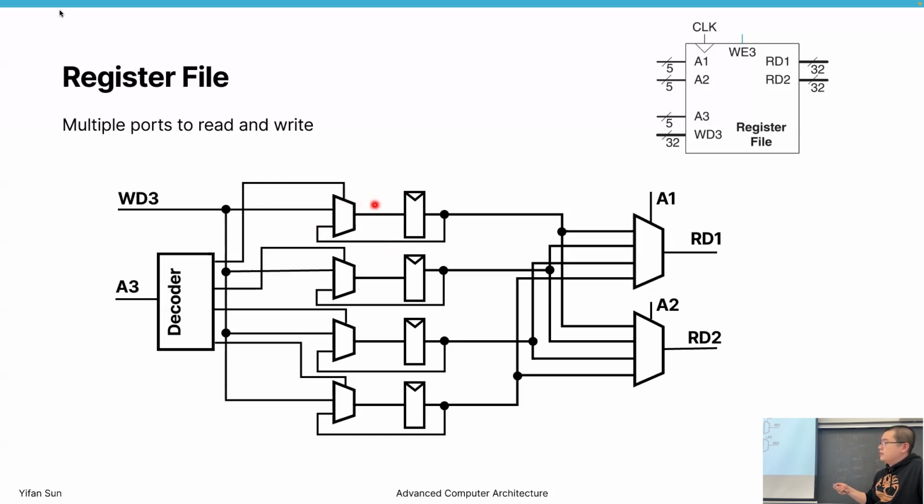So in the next cycle, the data loops back, and we're writing the same data back to the register. Since the transistors are not flipping, we're not spending a lot of energy to keep the data stored in this register. But if we want to write the data, here we have a selector, right?